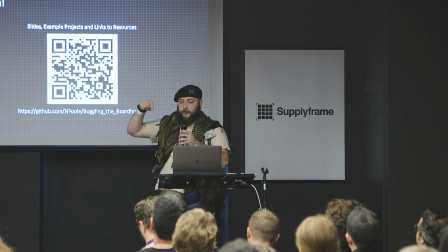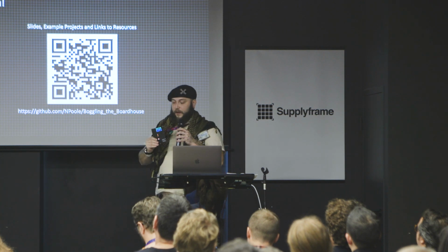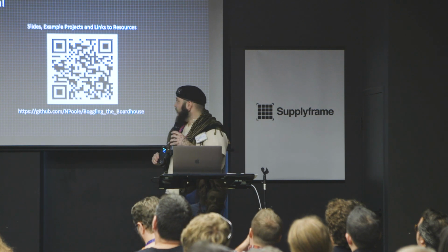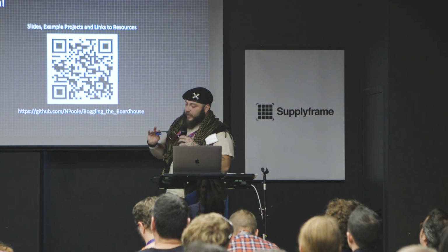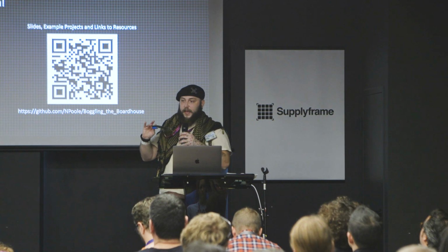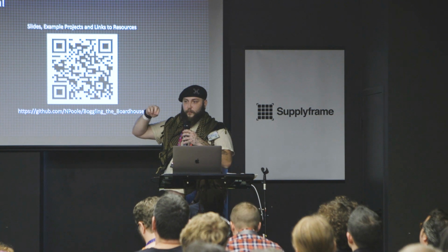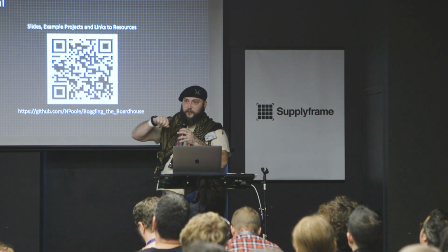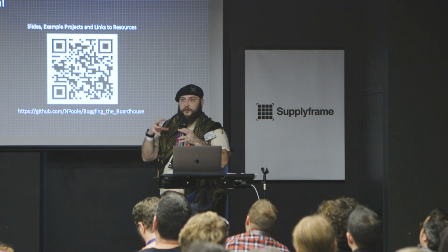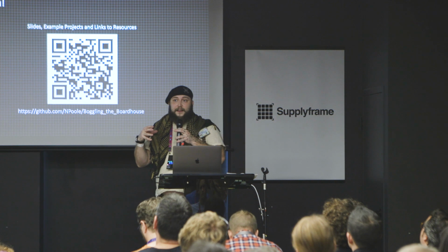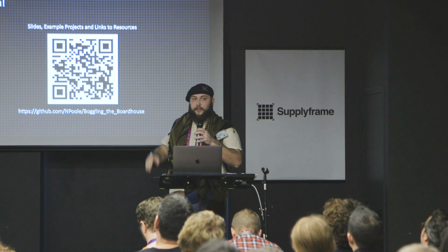Another way to do it is to just put drill hits all the way through all of your boards, and this is what I did for the Space Invaders badge, the Cosmic Aggressor badge. I just have plated through holes on every layer, and then I take a single pin header and put it through and solder it on one end, then smush all the boards together and solder it on the other end and clip it off like a little rivet, and it just sandwiches everything together. And the nice thing about that is it's really simple to take a soldering iron, touch it real quick, peel that top board back off and take everything apart for repair.